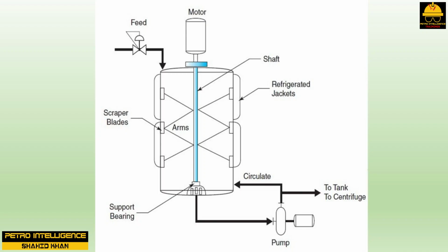An example of the use of crystallizers is in the production of paraxylene. A feedstock of metaxylene, orthoxylene, and paraxylene is fed into a series of empty vessels. Inside the vessels are rotors that turn constantly. The rotor is attached to a series of mechanical arms. These arms reach to the sides of the crystallizer. At the end of each arm is a fibrous scraper blade.